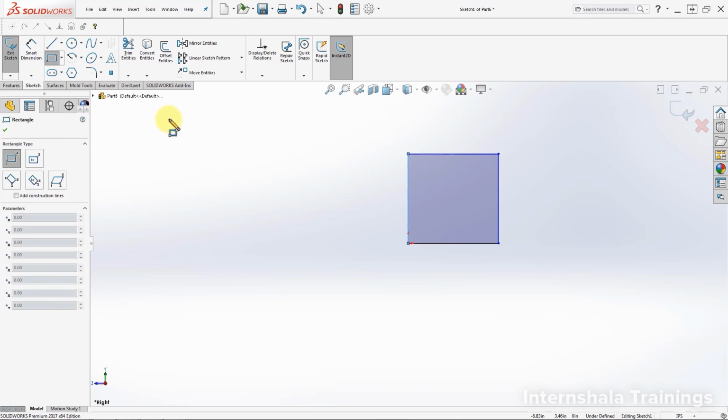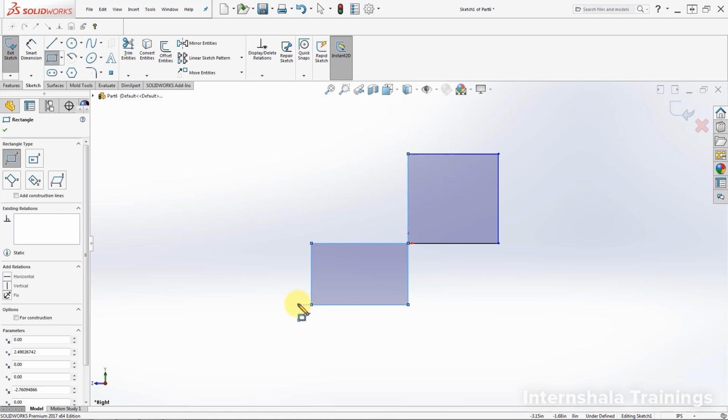And then go to the canvas and click on the origin, one click, and start moving the mouse. And you will be able to see how the rectangle is being formed using the two corners. If you click again, you will get a rectangle. Now let's check out the other option. We go back to the drop-down menu and click the second option, which says center rectangle.